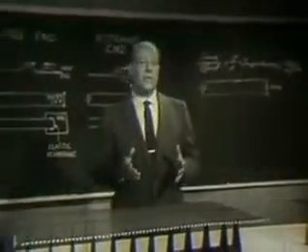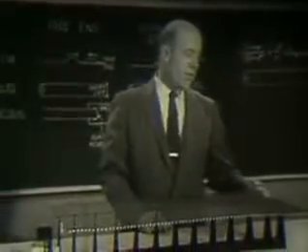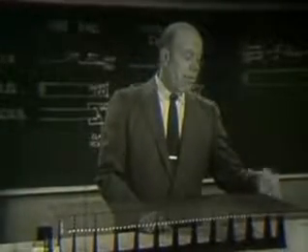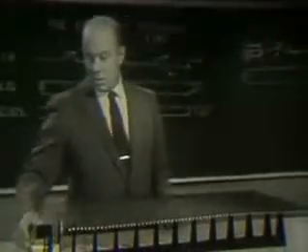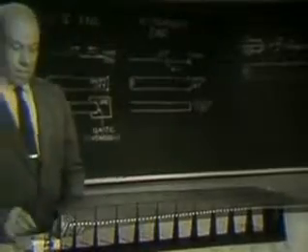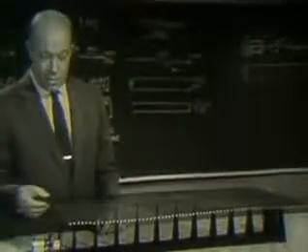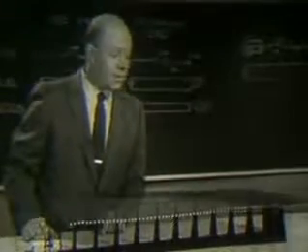Now, this matching condition can be demonstrated very nicely with the wave machine here by attaching to this last cross arm a mechanical impedance and adjusting the resistance, the counter torque, with which that impedance reacts back on the motion of this cross arm. Such a mechanical impedance is afforded by this dash pot, simply a tin can full of water with a little piston pumping up and down in it. By sliding this dash pot in or out along the last cross arm, I can control the counter torque with which it resists the displacement of the medium, and thus match the impedance of the dash pot to the impedance of the transmission line itself. When this adjustment is properly made, the dash pot absorbs all the wave energy that travels down the line, and as you can see, hardly any perceptible reflection takes place.